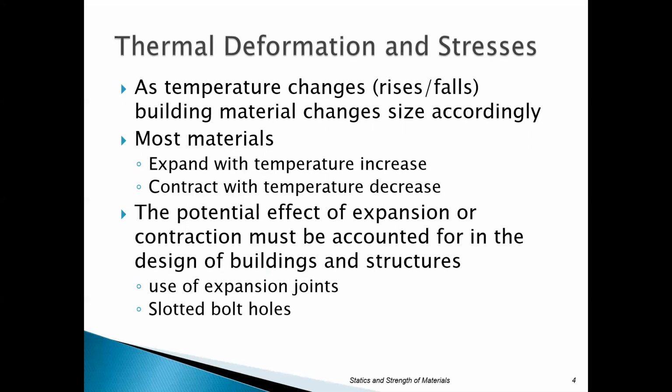That potential for expansion really has to be accounted for in the design. And as we said, it's accounted for a couple of ways by using the concept of expansion joints. Those can be physical joints that you see, like I said, on a bridge, and then underneath you'll probably have a roller where that thing can roll across with it. And in concrete, they either form those joints in there, or they'll come back and saw cut. You've probably all seen that.